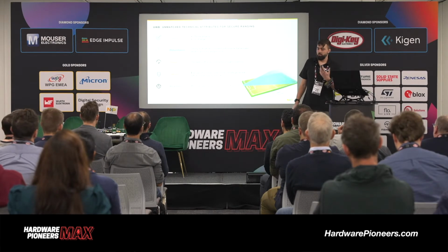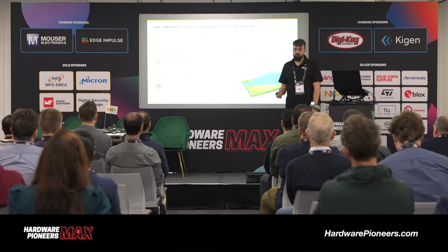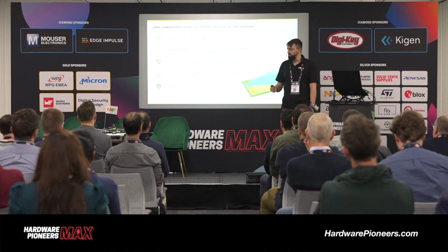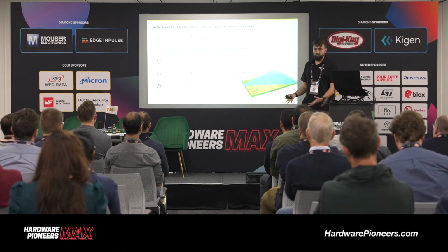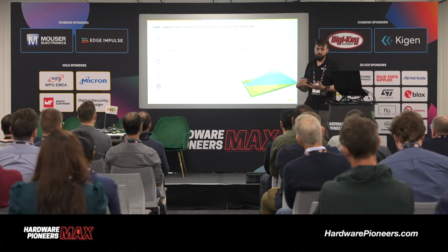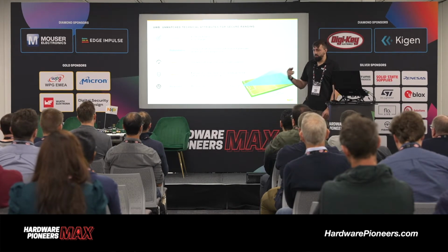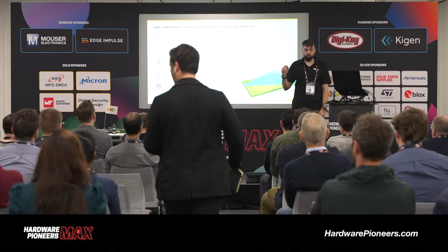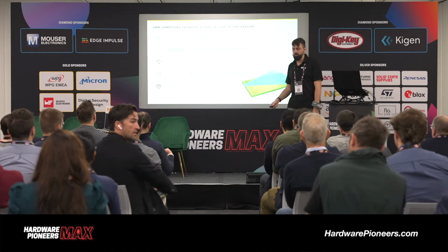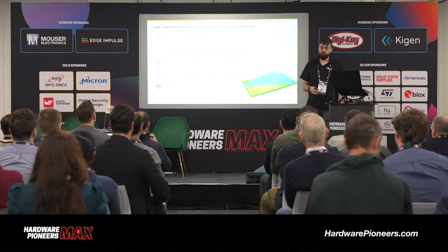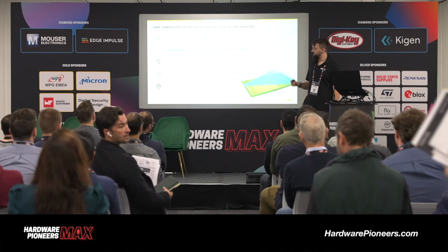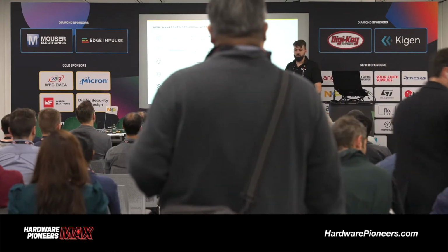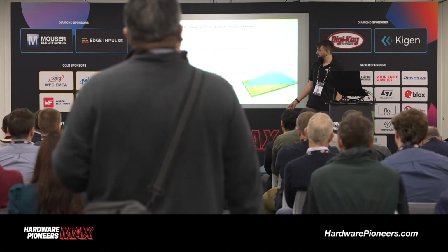Another feature which is very important for ultra wideband is its robustness. It's very resistant to multipath and other interference from other signals due to its unique features. Its range is also quite good, as much as 100 meters in line of sight conditions. In the IEEE standard, the security of this protocol is very good. We can cryptographically secure every part of the ranging message, so that attackers have it even harder to attack this communication technique. Also, it's real time. We can do update rates up to 1,000 times a second, which is awesome.